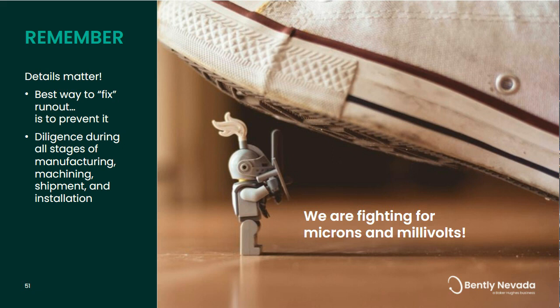making sure that the probe target areas are properly wrapped and protected so they don't get rusted. And the installation side of it, making sure that the right tools are used when barring the machine over or rotating the machine so that the probe surface area isn't affected. All of this works together and the details matter. We're fighting for microns and millivolts when we're looking at vibration here, and every little bit helps.